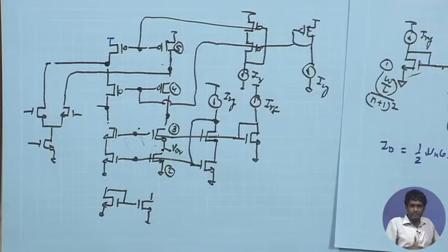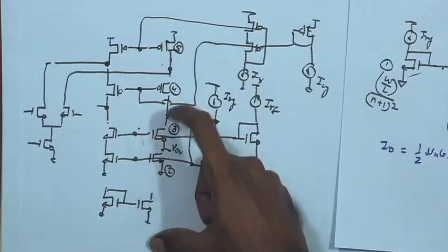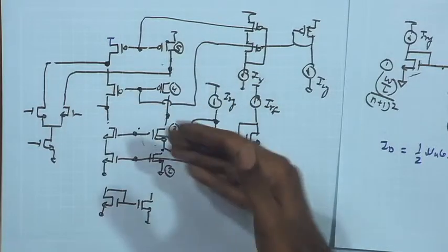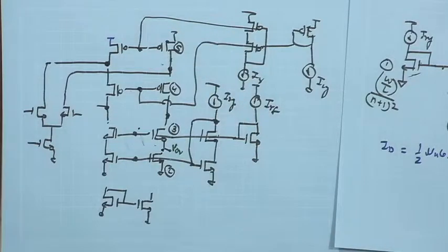And in this case, it will be relatively simpler because you have self compensation present in this amplifier. So, once again both the common mode and the differential loops will be satisfied with the same dominant pole. Here that advantage is missing, that you can separate out the differential and common mode loops. Because you have a single dominant pole, you will end up compensating both the loops with the help of this dominant pole. But we still need to figure out the common mode feedback configuration, the configuration of the error amplifier, where to apply the input, where to apply the error amplifier output, and so on.